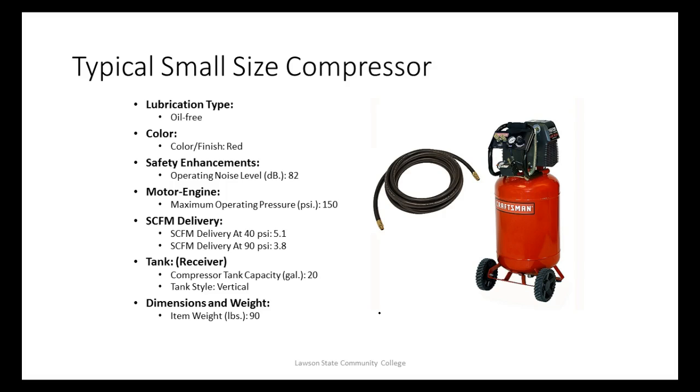This is only 5.1 cubic feet per minute at 40 psi, but only 3.8 if you're operating at 90 psi. So this would be our flow rate.